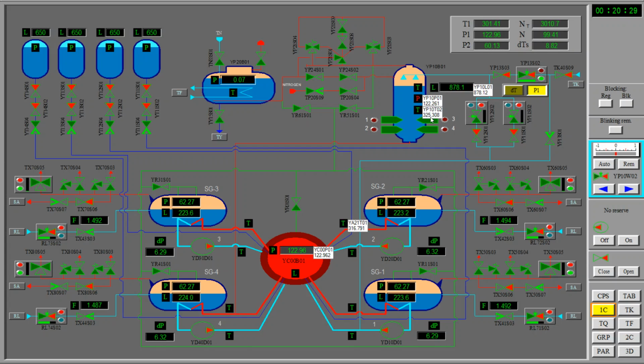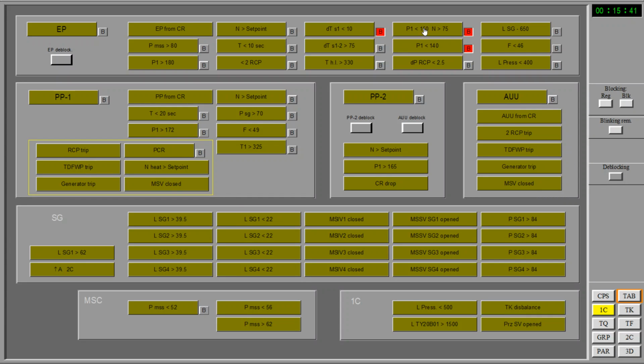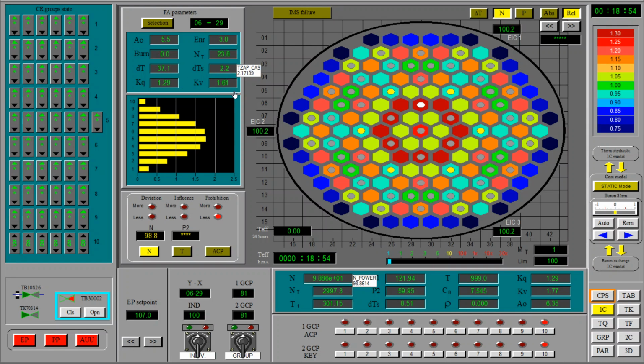This means that if the temperature between pressurizer and reactor or any of the legs of the primary is higher than 10 degrees, or better say the hot legs is higher than 10 degrees, this will create a scram. So well done disconnecting this. Should I disconnect something else? For the moment, no. We're at 2.2 degrees of boiling.